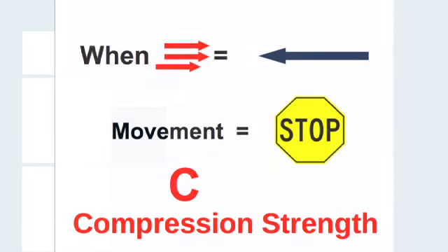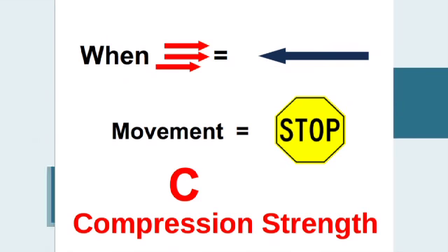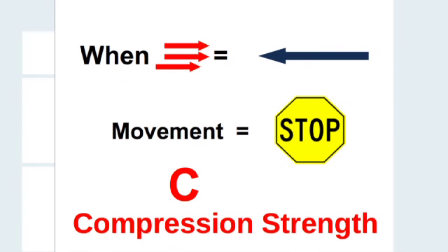Here's a sketch showing that when particles move across each other, there is a movement and an increase in volume. Compression is a decrease in volume, whereas failure is an increase in volume, and a dilation takes place. And the dilation is the degree of expansion that must take place before the particles actually move over each other.